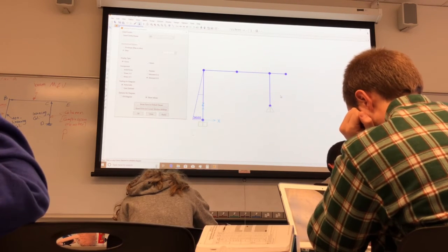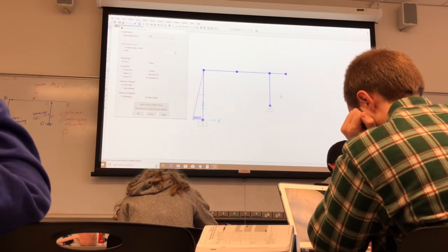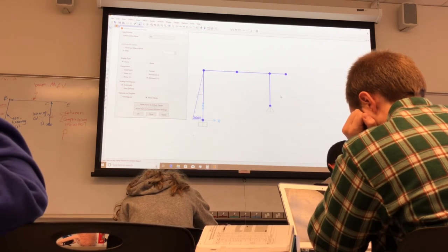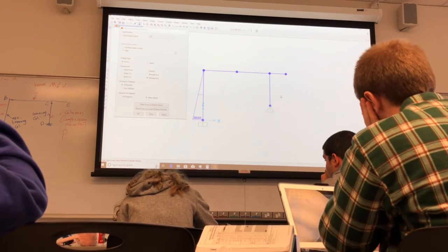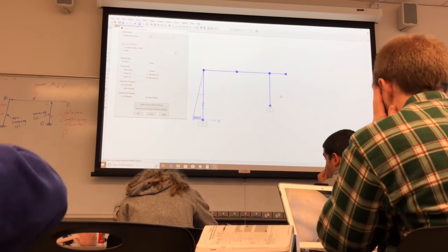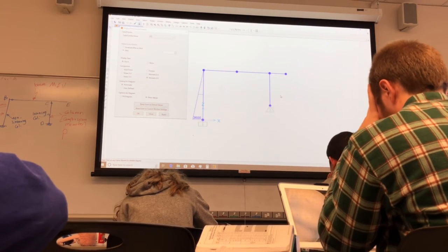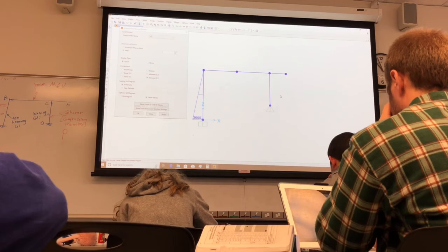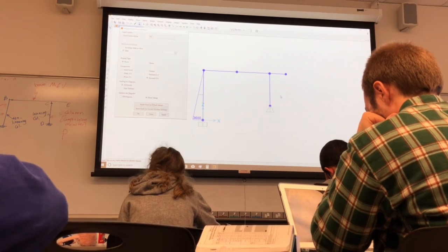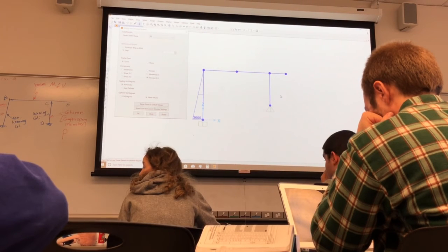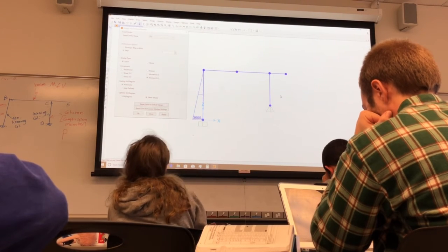So here we have 0 wind and 0 earthquake. We create this table for load, we call that the load cases table. Now these are service loads, that's why I put the P, and I can call here that's service. That's the loads the structure sees every day, all the time.